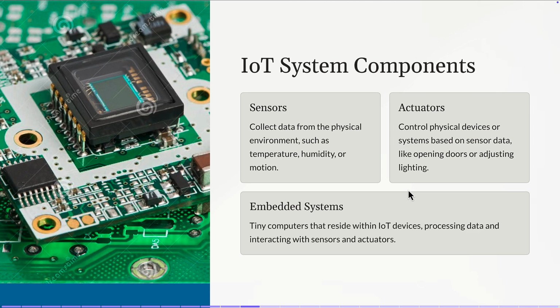So sensing is one of the energy dissipation issues. But there is an even more dramatic issue. Which one? Communication. Communication is devastating. If you use Wi-Fi, you're going to consume quite a lot of power. There is low power Wi-Fi right now, but it's still good for several IoT devices, especially if they are mains powered. But if they are battery powered, there are other viable solutions, like a solution that you already know.